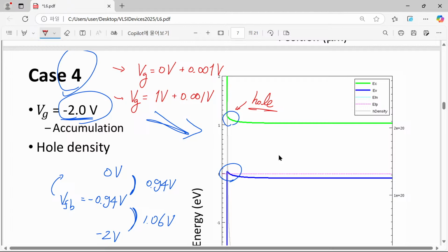So if it already has so many electrons in it, then small changes in your voltage will introduce a large electron density increase. However, if you don't have much electron density in it, then you will have quite a small increase of your electron density. This is a key point to understand the behavior of your silicon electron density. I will revisit this once again with